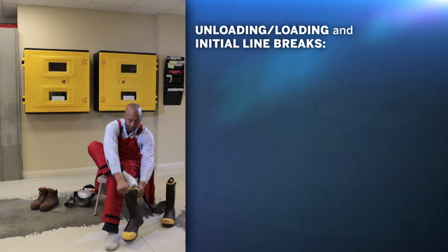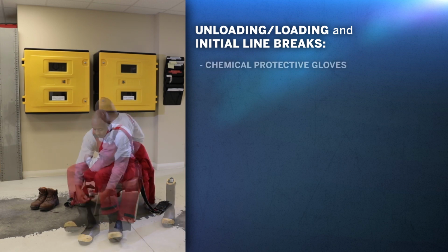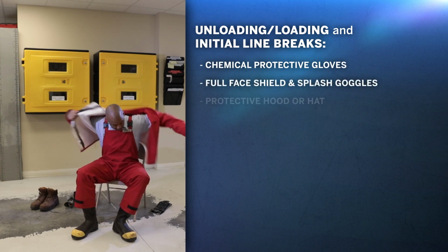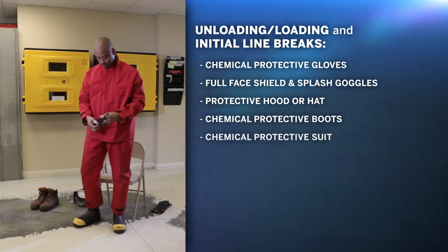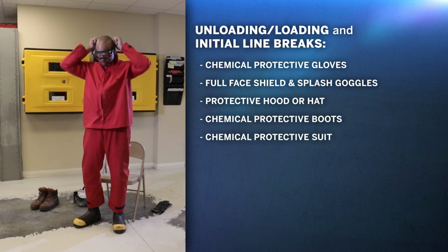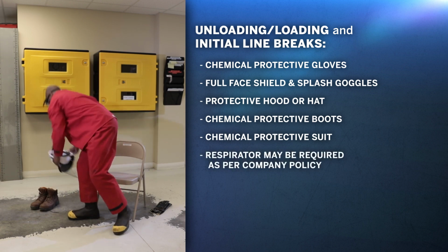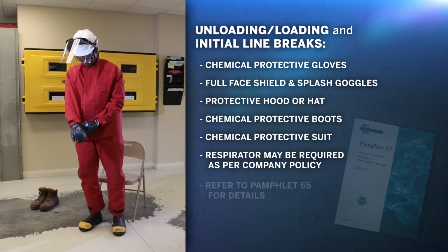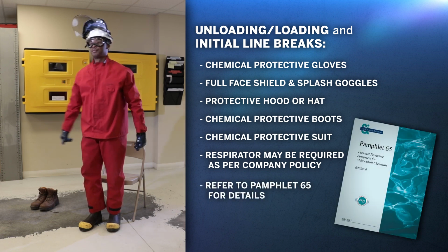When unloading and loading shipping containers or performing initial line breaks, chemical protective gloves, a full-face shield and splash goggles, protective hood or hat, chemical protective boots, and a chemical protective suit should be worn. Your company's air testing results and policy will dictate whether a respirator is required for any or all of these activities. Refer to Pamphlet 65 for more details.